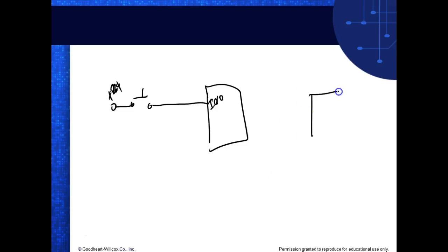Well, what are we going to put on this side? So here, this is going to come over to my PLC input. Let's say this goes to input 0/0. Well, if I come over here and put this up to plus 24, it's got the power to it. So this guy here is going to sink that. The input port would use this as the common, and then my input device would hook up to this.